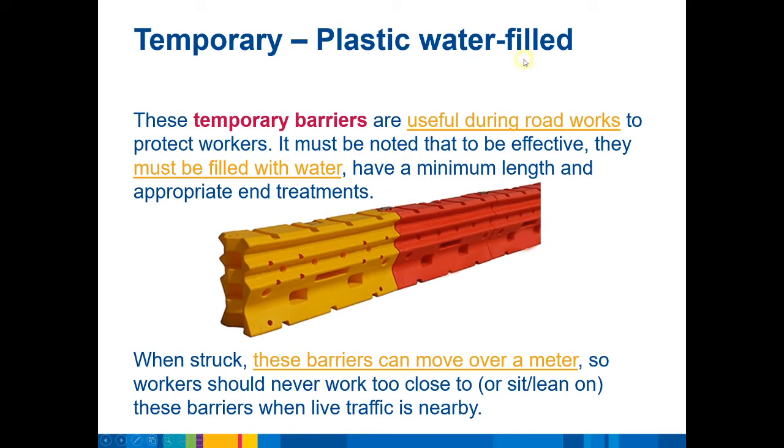Now, to be effective, these barriers must be filled with water. They're called water-filled, not, I guess, hydrophilic. They don't like water, they need water. They also need to have a minimum length, and they need to have appropriate end treatments. So you need a certain number of these joined together, and they need to be filled with water. Quite often, I've been to inspect traffic management, and these are simply not filled with water.